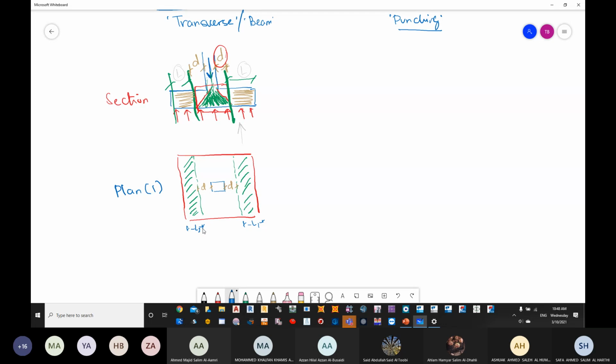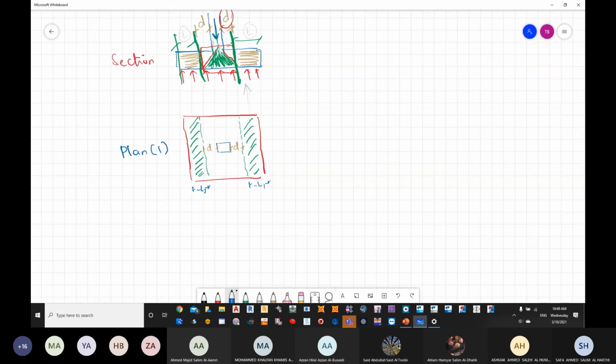Whenever I increase the length, the bending moment will increase. The same scenario, if I increase my L, my shear will increase. So from whatever lengths are given, you need to take the highest one. Now this is in one direction. You can see that these two areas are happening in one direction, so you need to take either the left or right, depending on which one is higher.